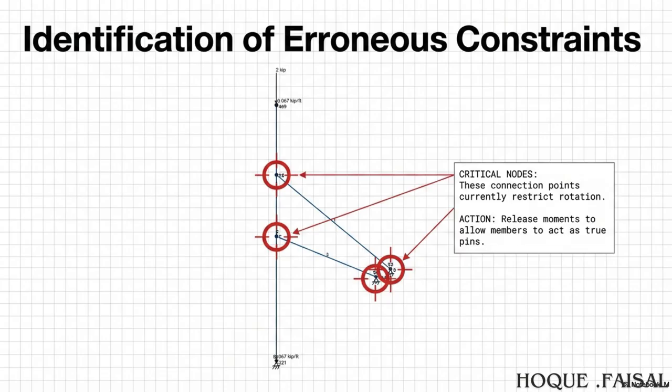I noticed one other little inconsistency in the report that seems to hint at this confusion. Right at the top, in the job setup, under general constraint, it says RRRRRR. The default setting for all members, all released. But then when you get down to the specific supports table, it overrides that default with things like FFFFFR. This is a classic sign of someone fighting the software.